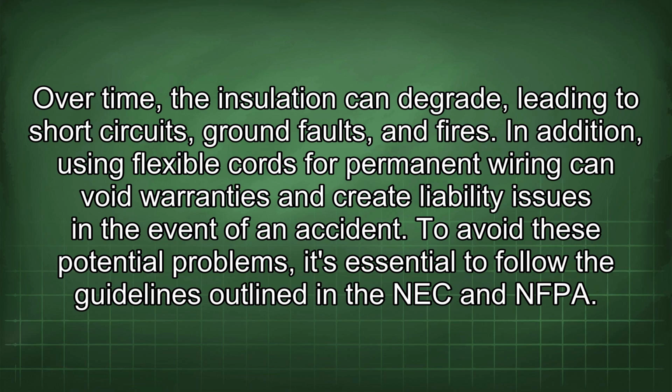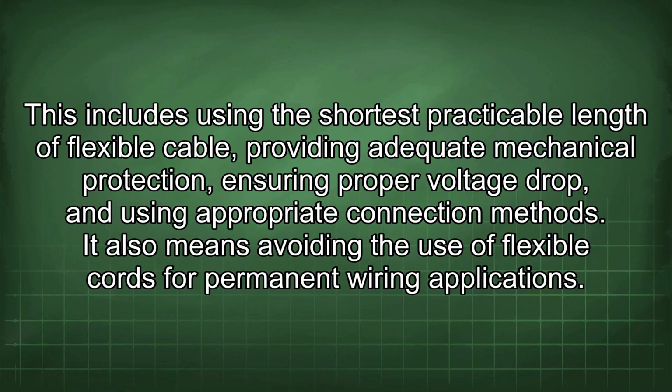To avoid these potential problems, it's essential to follow the guidelines outlined in the NEC and NFPA. This includes using the shortest practicable length of flexible cable, providing adequate mechanical protection, ensuring proper voltage drop, and using appropriate connection methods. It also means avoiding the use of flexible cords for permanent wiring applications.